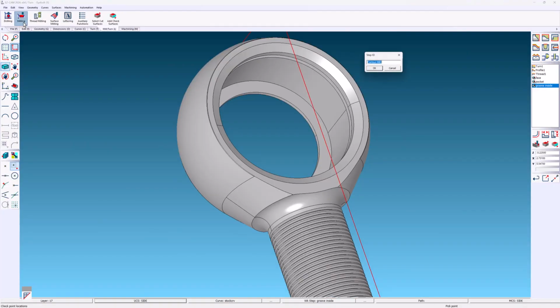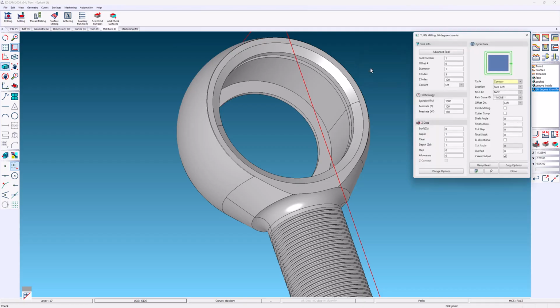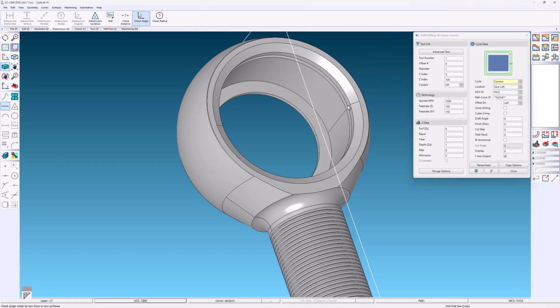A tapered surface uses a contour operation as well. Let's verify the surface's taper angle to make certain it is 60 degrees. Notice the operation window can remain open as we do this. The bottom right displays our angle. Don't forget to set the tool's taper angle.